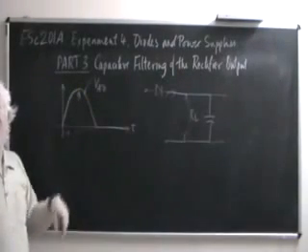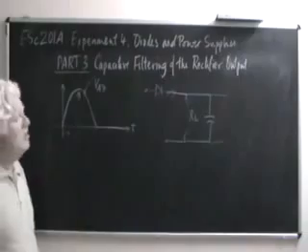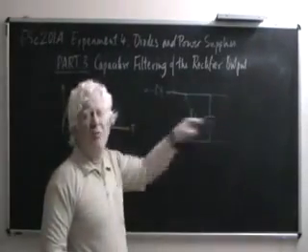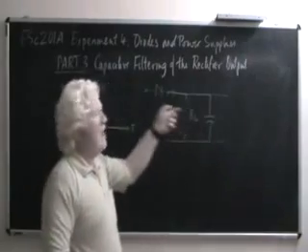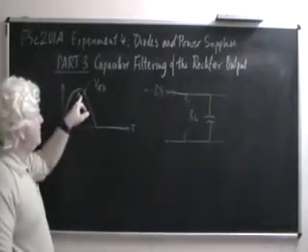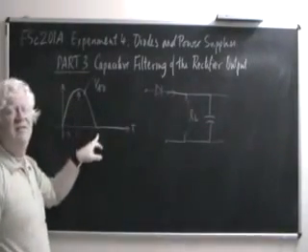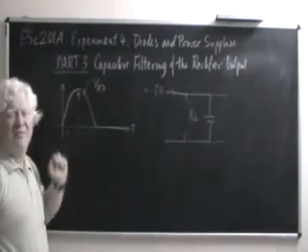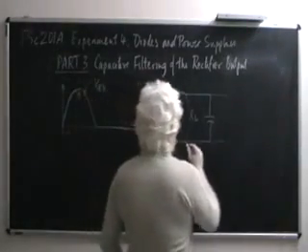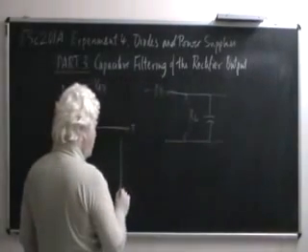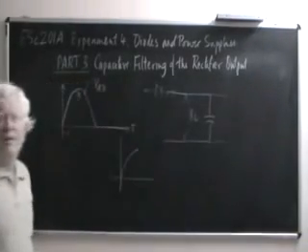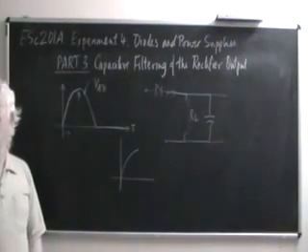After this, the anode voltage becomes lower than the cathode voltage. The cathode voltage is being maintained by the capacitor because it is now present, whereas the anode voltage has started falling. So the diode has got reverse biased at this instant rather than at this instant as was earlier the case. Essentially, the diode has only conducted in a quarter cycle, and after that, the diode does not conduct.